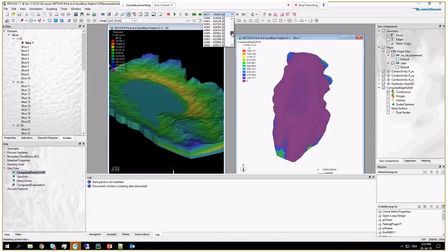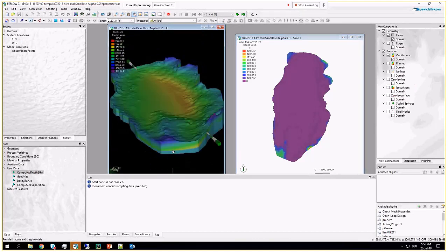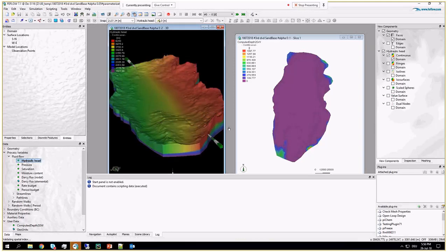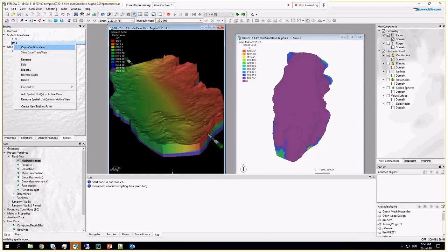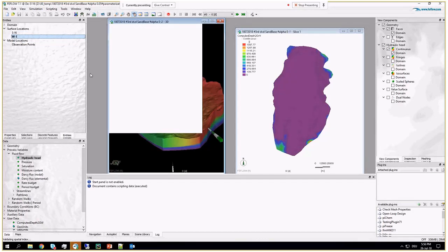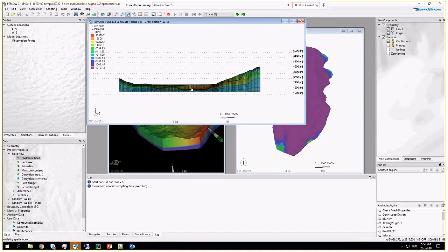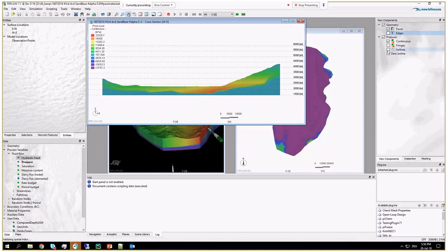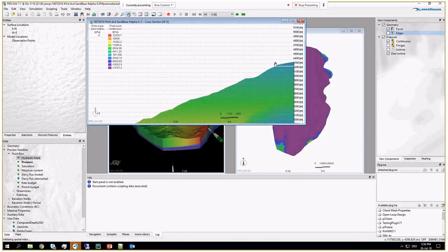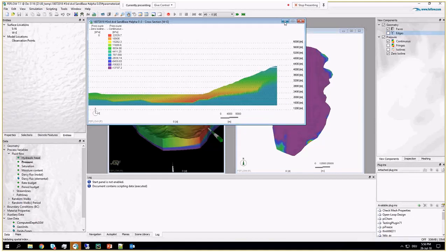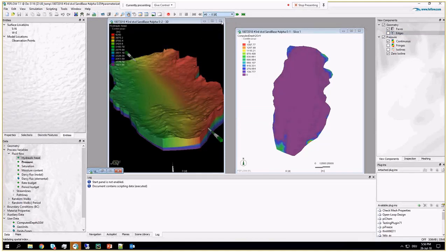And let me go and repeat the process here. So we start not from pressure 0, but from a condition where there is no evaporation, just the heads. So if I look at my hydraulic head here, this is my initial conditions. Then in this position, let's go to the cross section again. You can see, by the way, the mesh. So my entire profile is almost saturated. You see here the water level. I start with this condition, and now I start evaporating the system through the boundary condition.